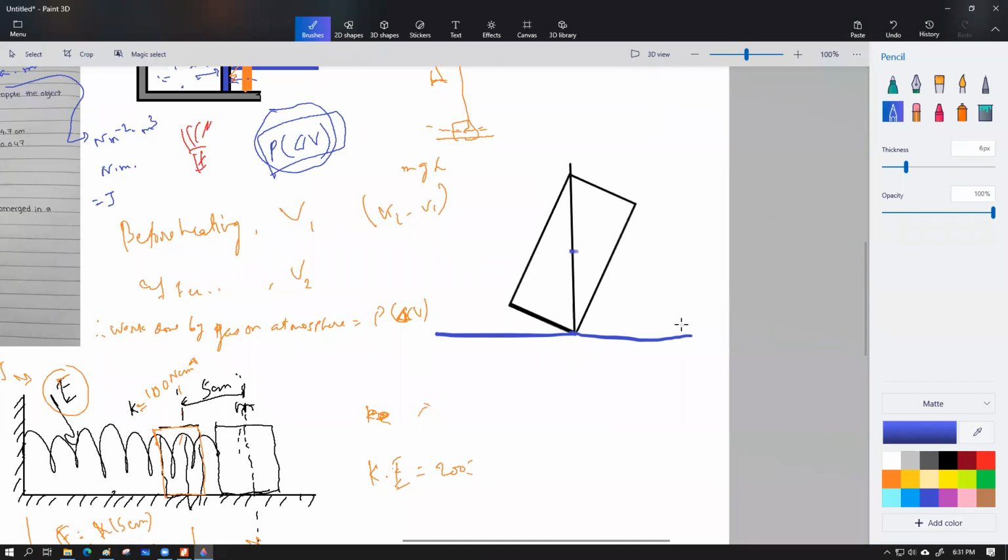Think about it. If you have a vertical object that is placed like that, how far do you have to push to make the object rotate till it starts to fall on its own? You have to push the object till the center of gravity is vertically above the corner point about which the object is pivoting. And as you push the object beyond this point, its own weight is going to rotate it further. So all that you have to do is to move the object from the possible vertical orientation.